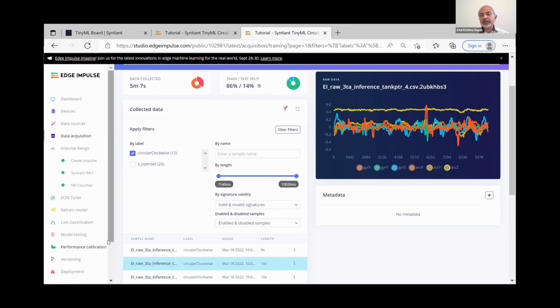So for certain cases where there is no start and stop of the event, like a vibration and things like that, this method would work. But if you have, let's say, something like you want to flick your wrist and you want to detect that, in this case, this is actually one event. And in that case, you don't want to be saving much longer. You save maybe 2 seconds before and after, and then align the data so that your motion is captured and it looks similar between the tensors.